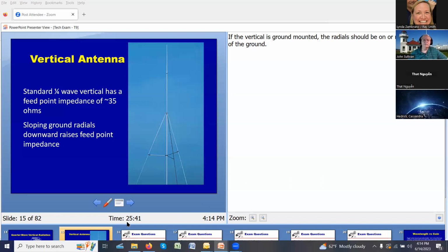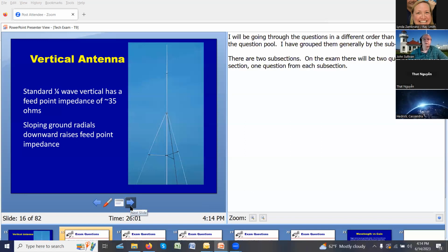And ideally, you want to have a feed point on an antenna that would require you to do nothing. It would be perfect at 50 ohms, because your radio is going to expect to see a 50 ohm impedance, and you would be using 50 ohm coax, so you would like to see 50 ohms. You almost never have that. There's usually some difference, but.